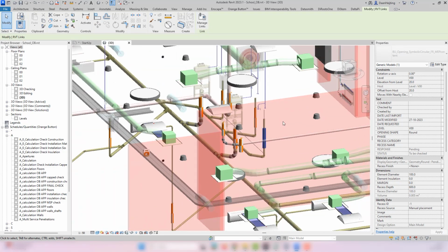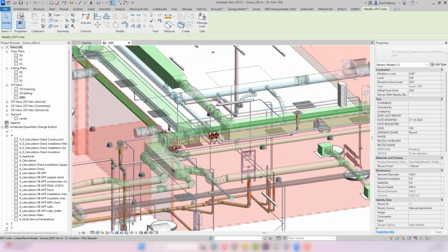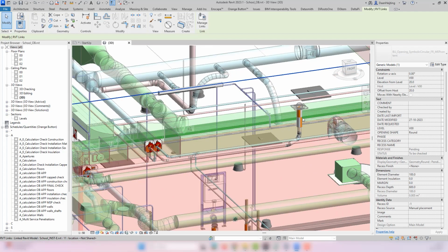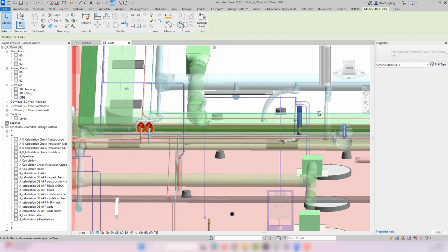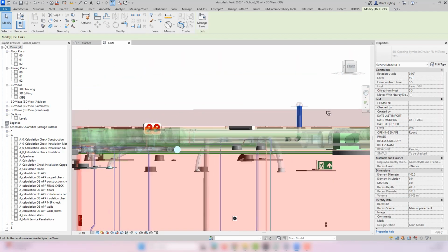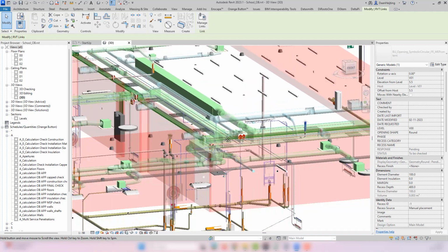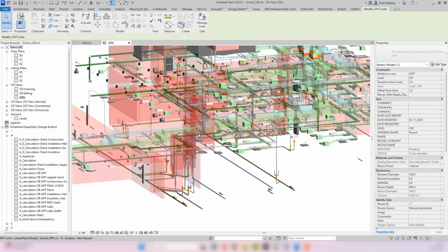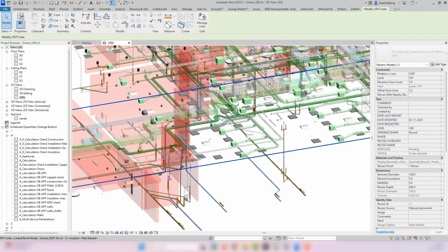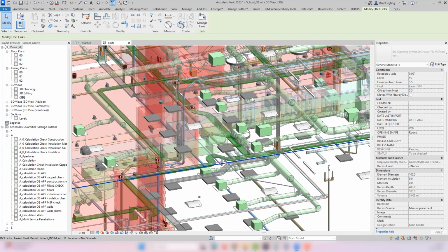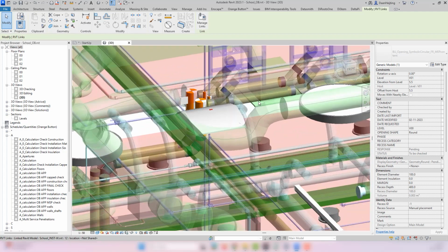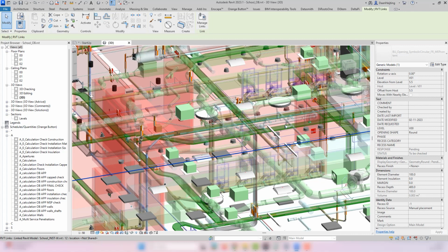More and more openings are modeled in the BIM environment as a physical BIM object. Most of the time, these openings are also planned for execution by the general contractor, leaving no space for optimization based on the selected firestop solution. For instance, if you use a filler, you will need a smaller opening than if you would use a mineral fiberboard solution.